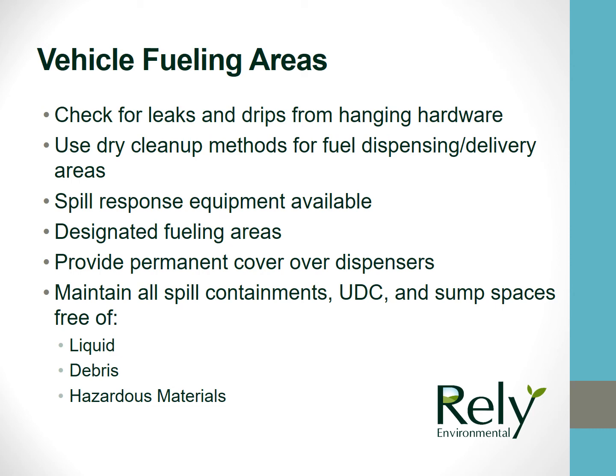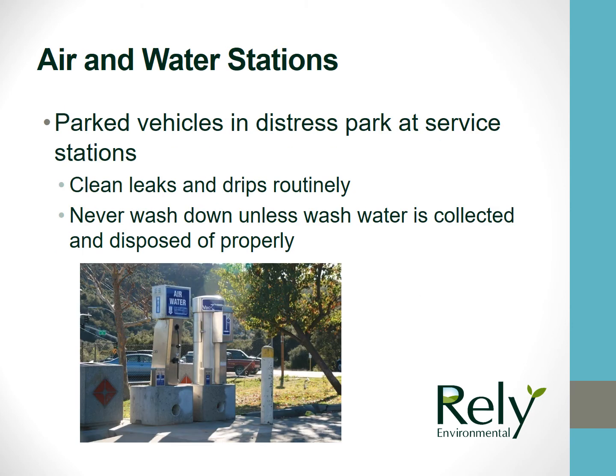Provide permanent cover over dispensers and maintain all spill containments, UDC, and spill sumps free of liquid, debris, and hazardous materials. Air and water stations are where vehicles in distress are most likely to park. Be sure to spot leaks and drips routinely to maintain the area clean. The area must never be washed down unless wash water is collected and disposed of properly.